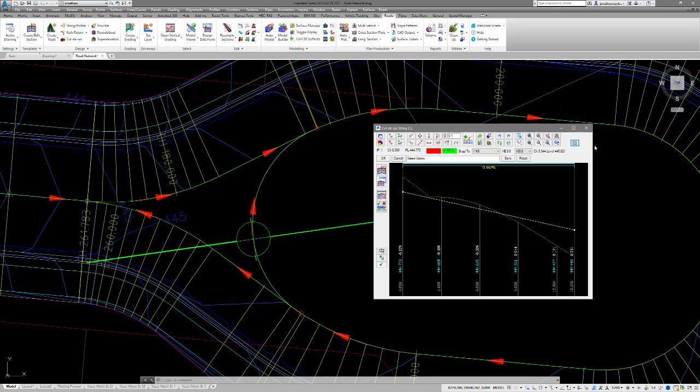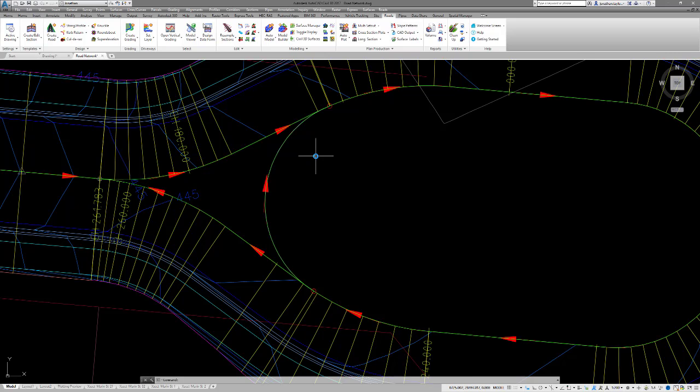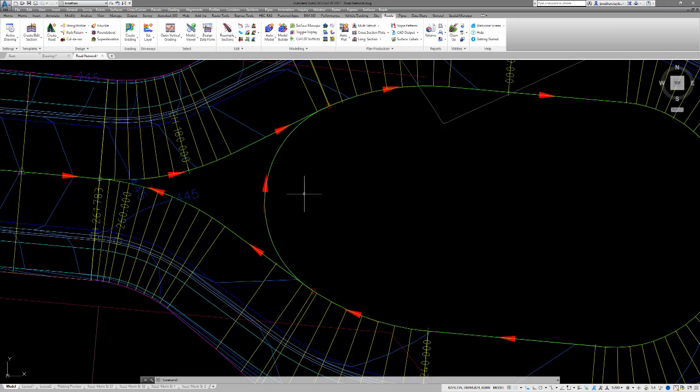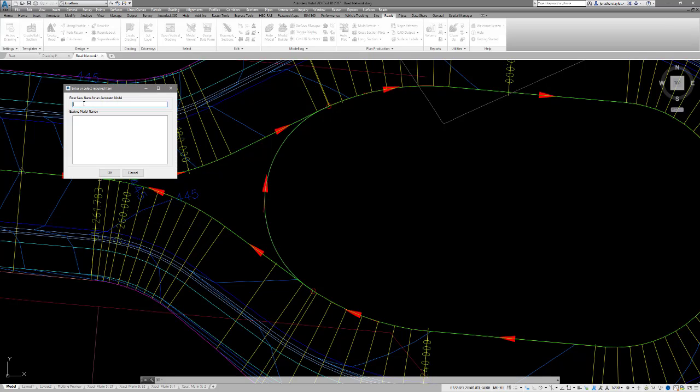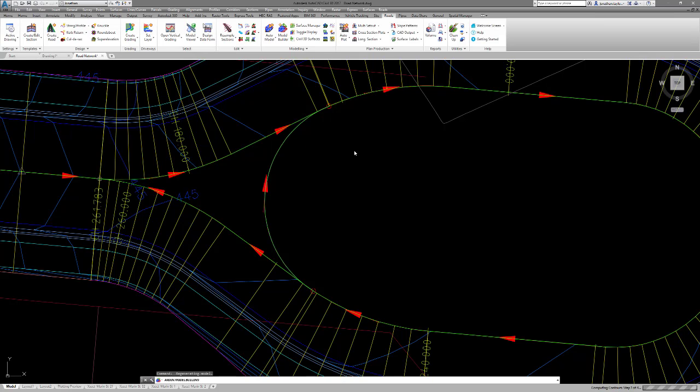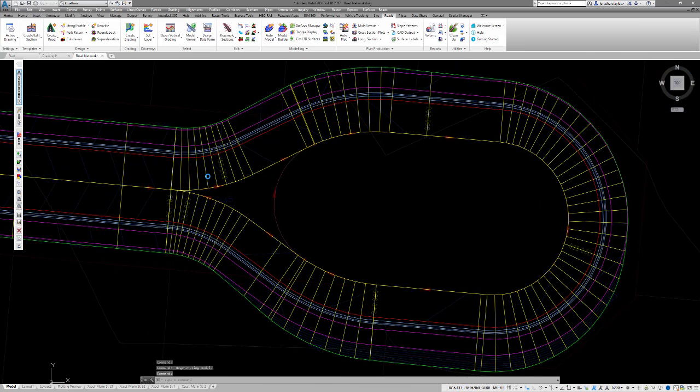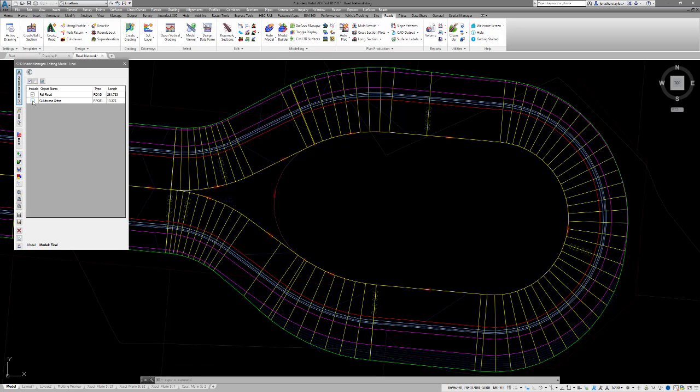Now those levels are set up correctly, I'm now in a position to add the string to this road model using Model Builder. So I click on Model Builder and I use Linked to Auto Model, which means use Auto Model initially and add this piece of design into it. I'm going to call the model Final, click on OK, and go to Include Exclude. You'll see Total Model has already been selected first of all, and we're going to add our cul-de-sac string, and then simply hit Build.